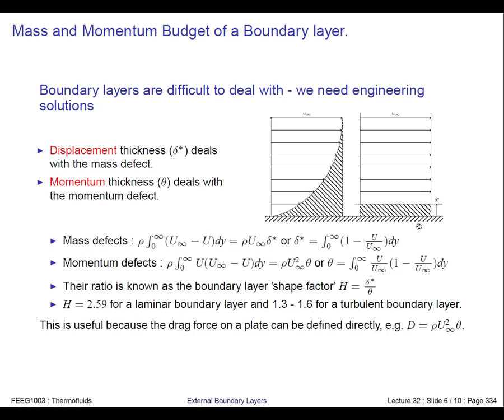This doesn't have a great deal of practical use, but the momentum thickness has much more use because you can calculate the drag with it. Okay, so let's have a look at how you define the displacement and the momentum thicknesses. So the definition is this integral here.